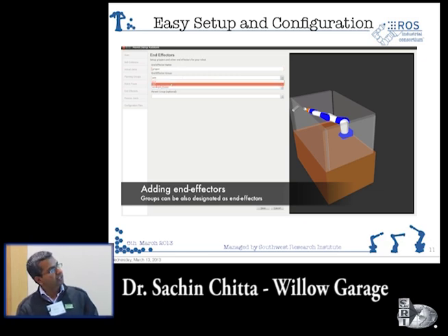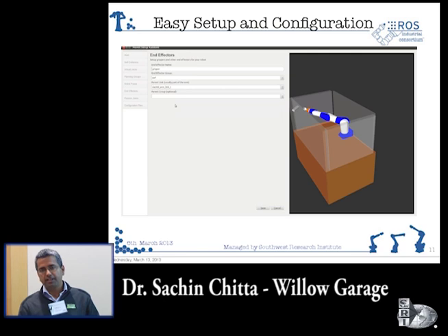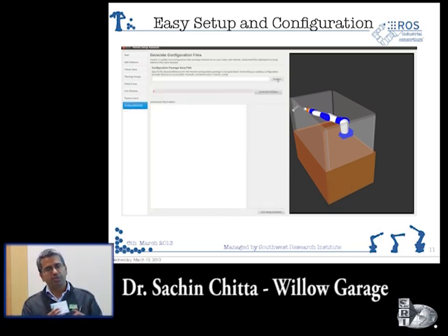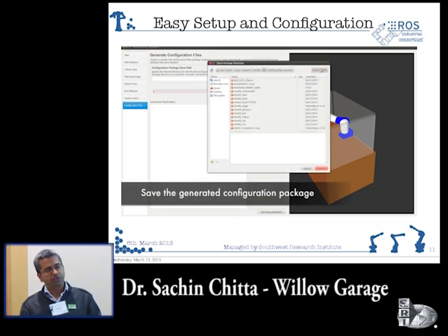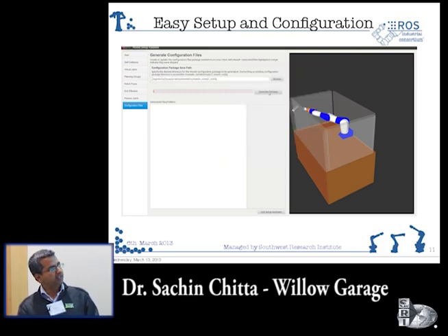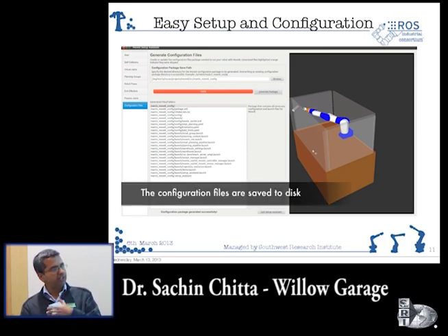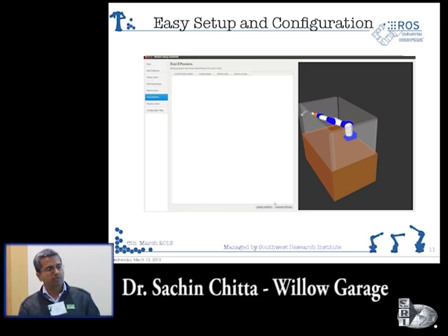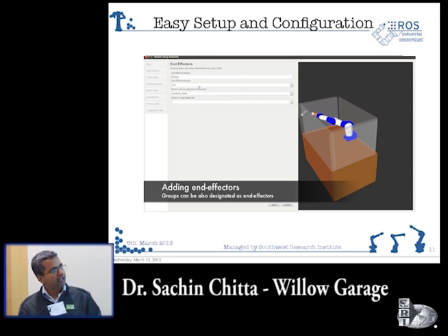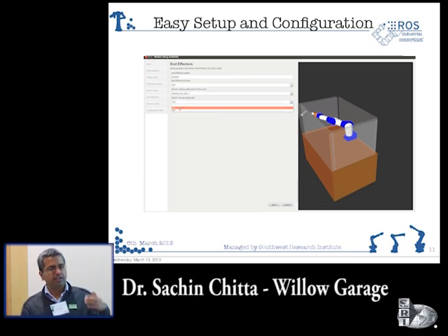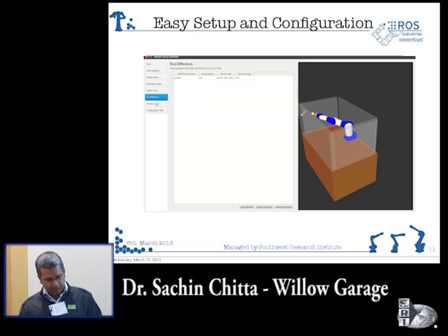The next thing that you can do actually is add certain configurations. So typically in robotic applications, if you need some fixed configurations, so the robot needs to be in some fixed configurations like a home position and then a particular manipulation position, you can add all those in using this tool. And basically when you're online, when you're doing your applications or motion planning, you can just refer to these positions directly and say, I want to go back to the home position or to XY position. Essentially, this gives you the advantage of addressing a set of configurations directly by name, and it makes application development pretty easy in that case.